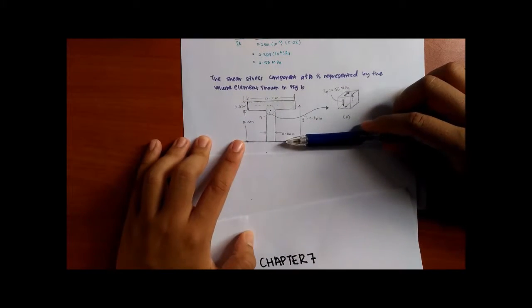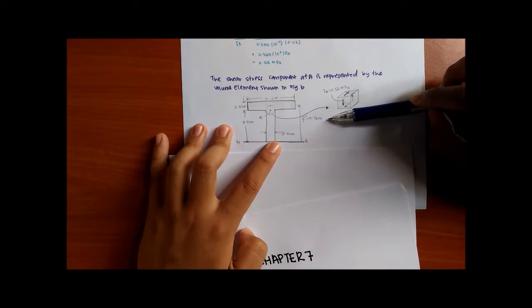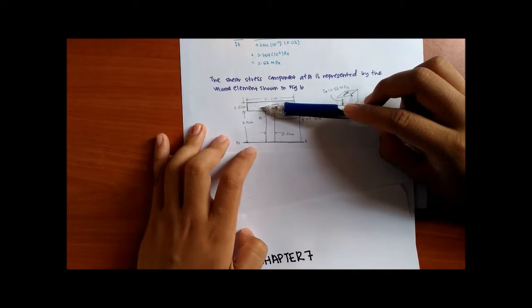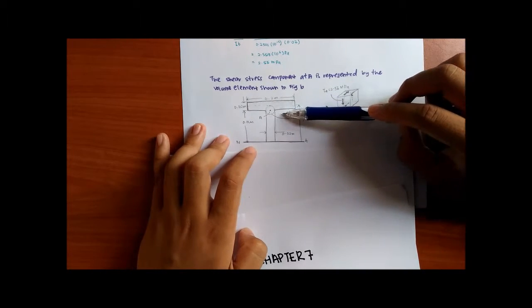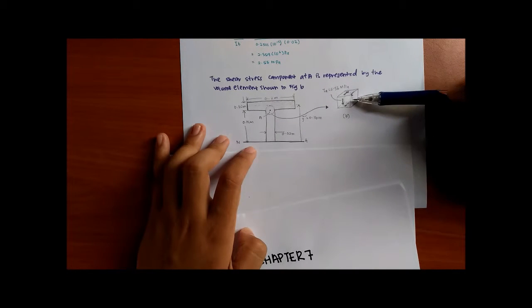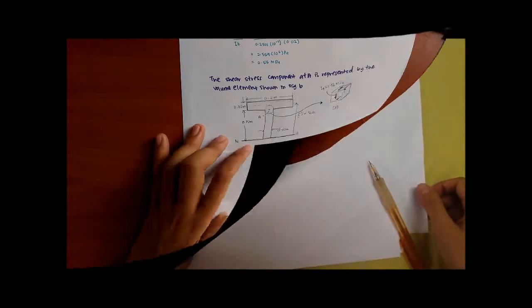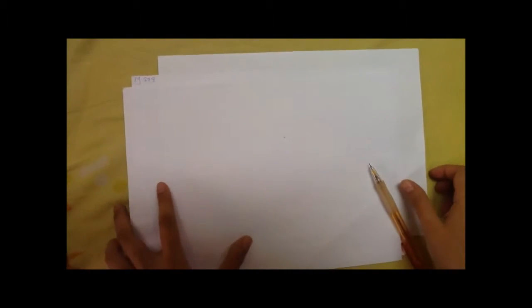We take from the neutral axis to the top, so we get this one. This Y bar is equal to 0.16 meter, and the distance from the neutral axis to here is 0.15. A is located here, so the volume element we can see in this figure B. This is the shear stress. Shear stress is a parallel force acting on an element. So the shear stress is equal to 2.56 megapascal. That's all. Thank you. I take this question from Pearson 9th edition, Mechanics of Materials, page 378.